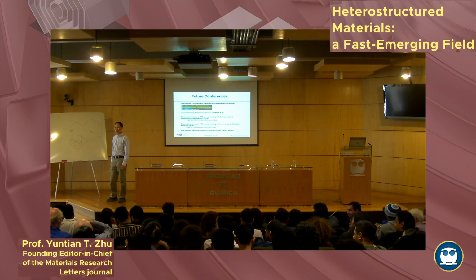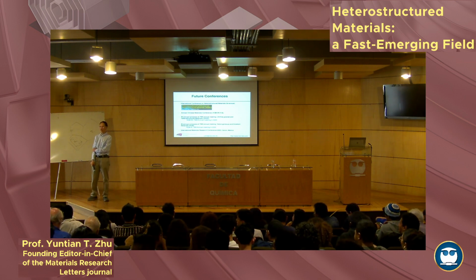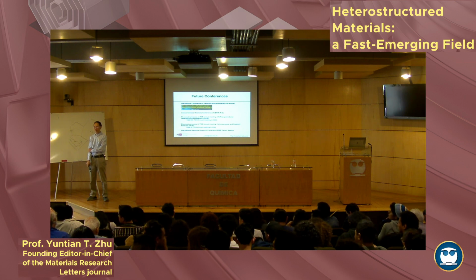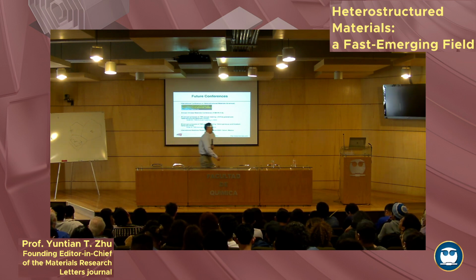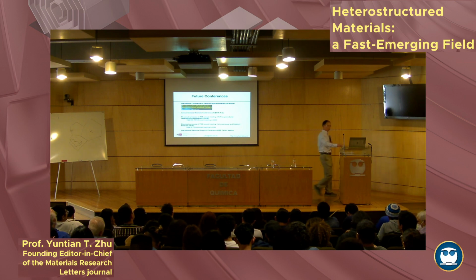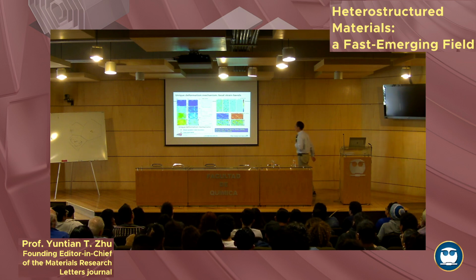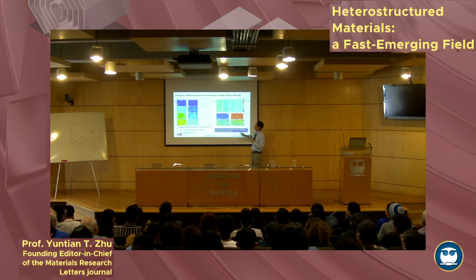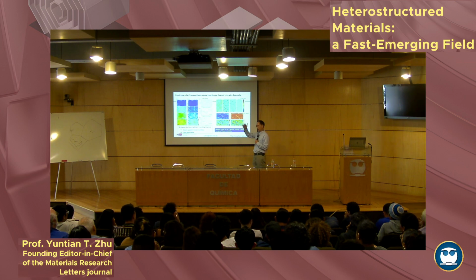Thank you. Last one, I promise. Well, it is regarding the final example you gave about brass, these strange lines that form after deformation. Have you made closer studies of, I don't know, even the composition or defects present in these bands? You are talking about the strain bands. Yes, exactly. We call these shear bands or local strain bands, and we don't know. We know there is dislocation pile-up. We don't know how this is related to that.